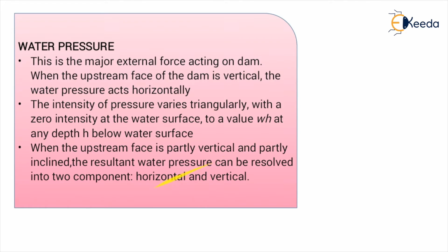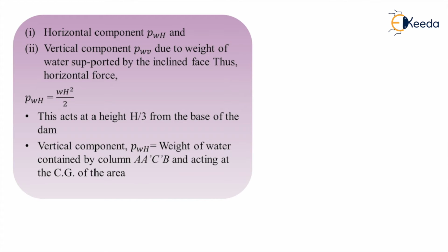And the horizontal component, that is half gamma h square, acts at a height of one third from the base of the dam.